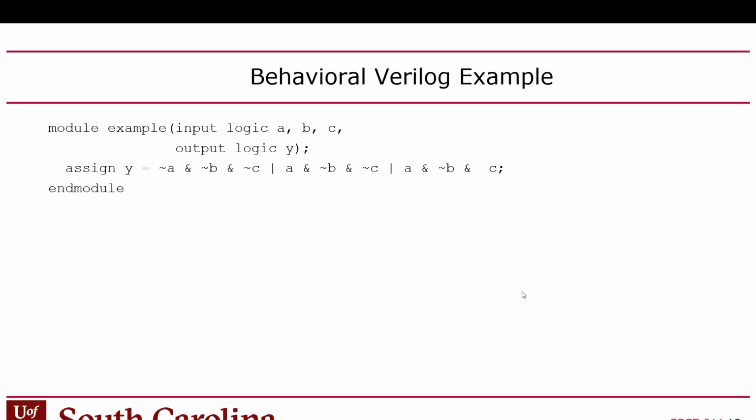When you synthesize, modules disappear because the hierarchy of your design gets flattened into one monolithic sea of gates and wires. That's completely unreadable, right? But the modules are there for the human factor, just for readability. In reality, they don't really translate into something physical in the real world. They're just virtual because, like I said, the modules end up getting flattened into just one big sea of wires.